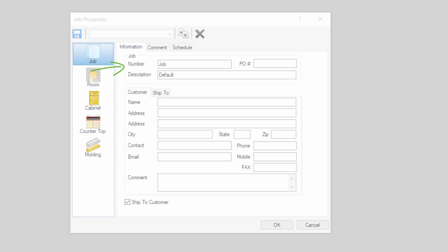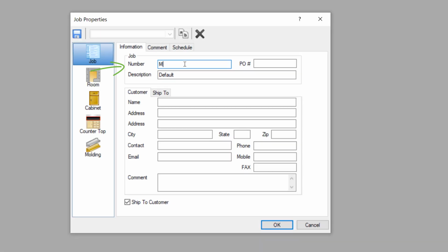This means you want to make sure you use a unique name for each job, and also make sure you don't use any special characters such as exclamation marks or hyphens, as this could lead to the job becoming corrupt, as Windows can't accept these type of characters within file names. So limiting yourself to numbers and letters in this field will save you a lot of effort long term, not having to deal with issues caused by this.